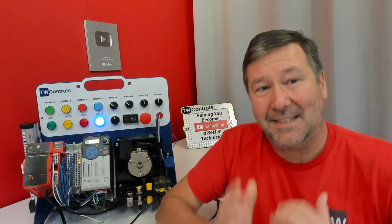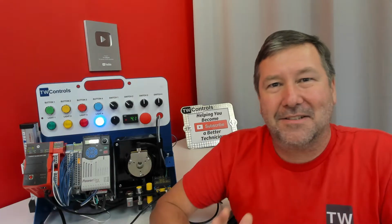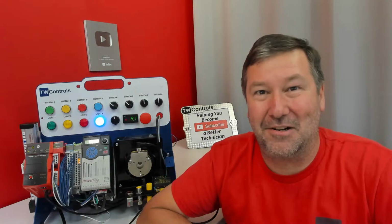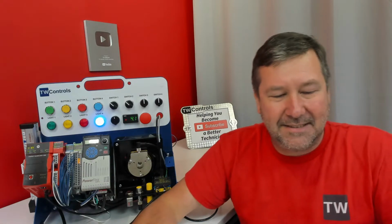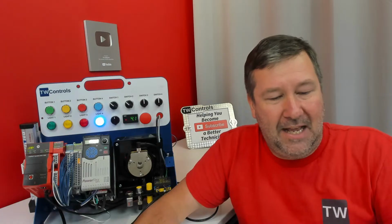And if you purchase one of our PLC trainers, the default IP address on it is 192.168.1.10. So the next thing we have to figure out is, okay, we know that now. How does our computer need to be configured? Or more importantly, currently, how is our computer configured? And so there's a couple of commands that we need to know that we can figure this out with.